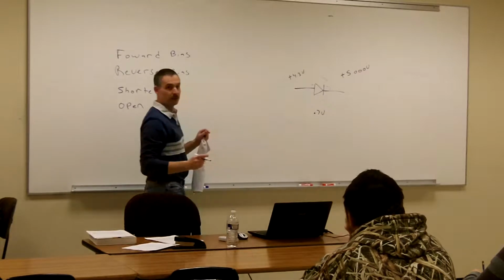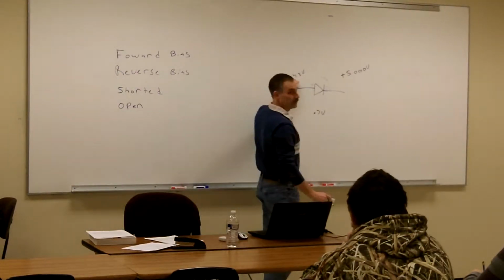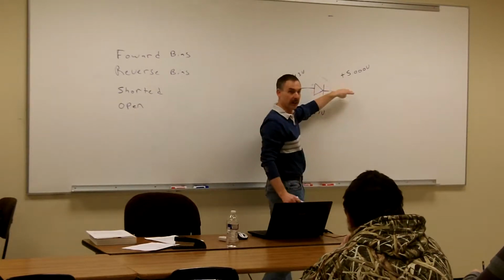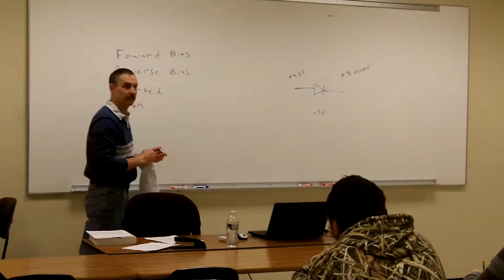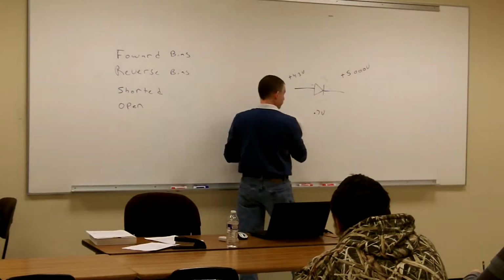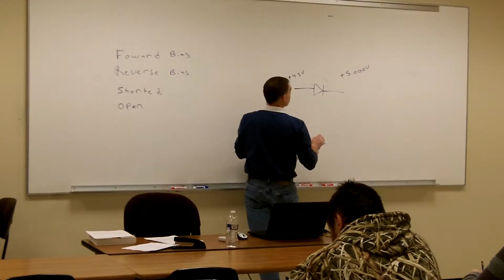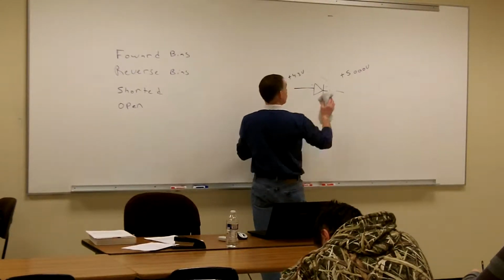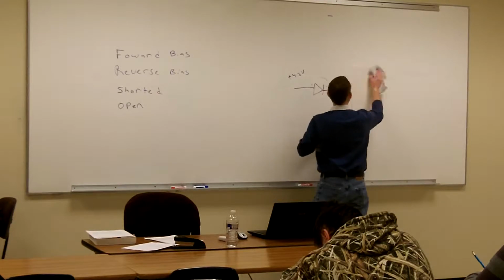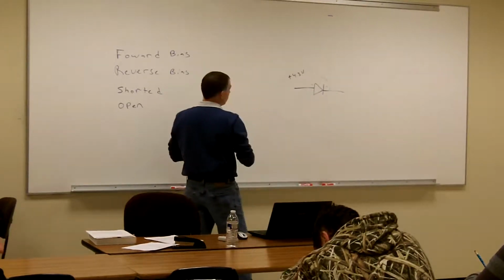So we know that my source voltage isn't 0.7, because we already have at least a plus 4 volts on this side and a plus 5 volts on this side. So that's how I realized that I threw in some bad numbers right off the bat there. That wouldn't be legitimate unless we had dual-ended power supplies, but we won't get into that.